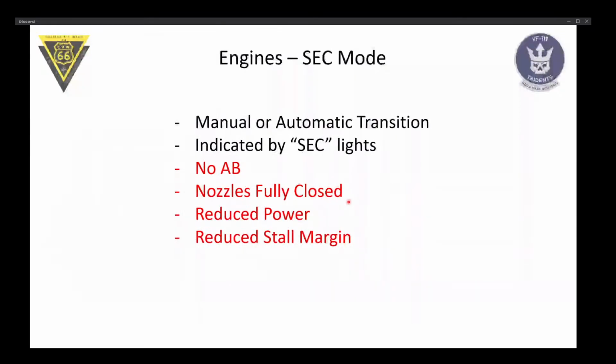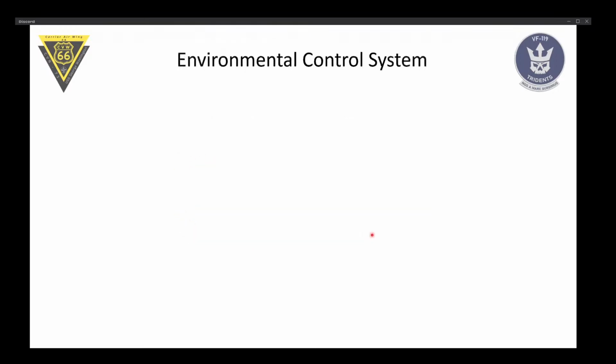Don't think this is something that DCS models, but high angle of attack, rapid throttle movements, stuff like that can make the engine stall. Not a big deal in primary, but in secondary this can become a problem. I think what DCS does model, if you try to go supersonic in sec mode, your engine will start to pop, which indicates compressor stalls. But which shouldn't happen, because since you don't have afterburners in sec mode, going supersonic is going to be difficult.